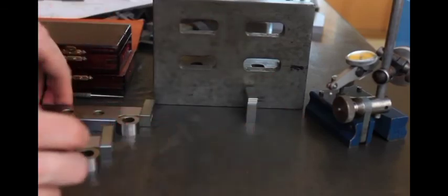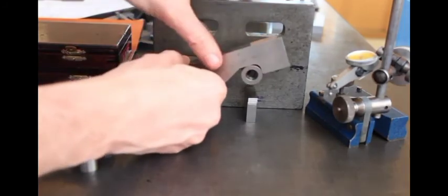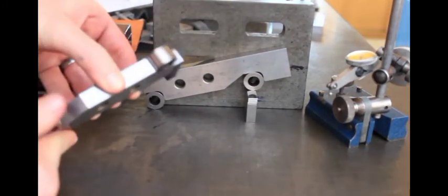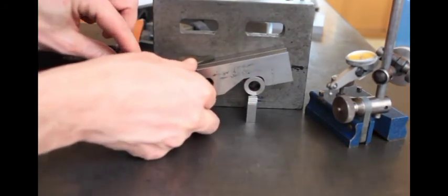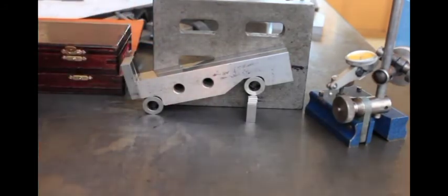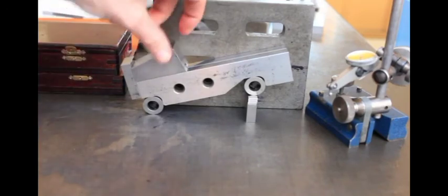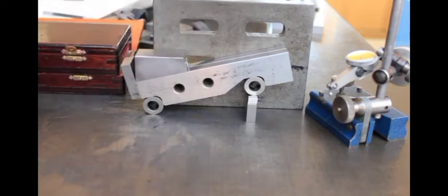Once we've got the slip gauge pile, we can place that against an angle plate. That section, I guess, is unnecessary but helpful for getting everything squared up. Now I'm going to use 2 sine bars as opposed to one thick one. I don't have one single thick one, and we're going to support our sliding block on top of there. If everything goes correctly, then we should create a flat surface there due to the two 15-degree angles.